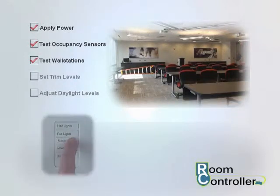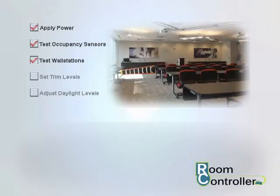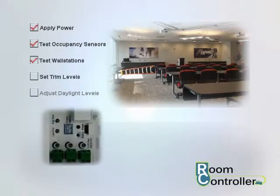Once wall station operation has been verified, if you are using 0 to 10 volt dimmable loads, for best operation and efficiency, set the appropriate trim level. Trim levels have been preset to approximately 90% maximum. Additional energy savings can be gained by adjusting this further if electric light contributed is over the target illuminance for the space. Trim level adjustments are done using adjustment dials on board the room controller.